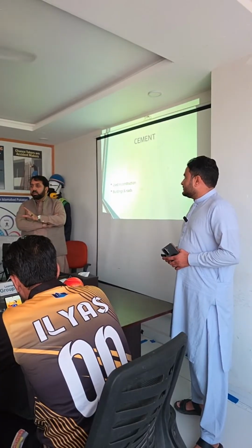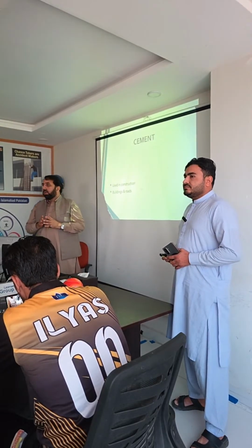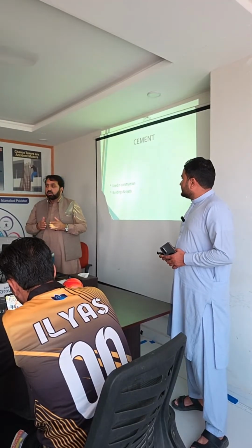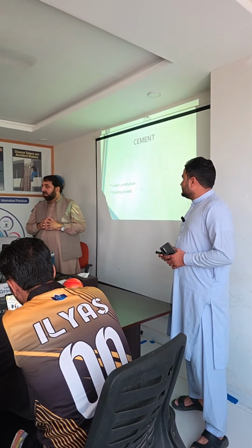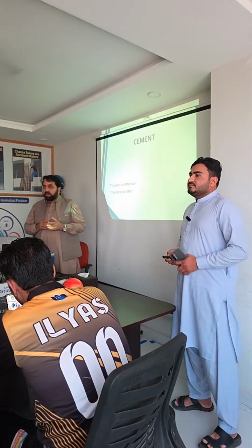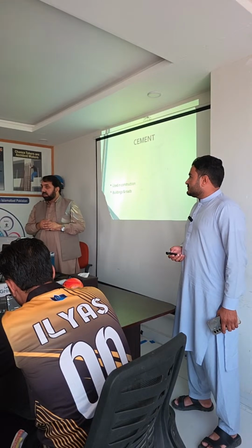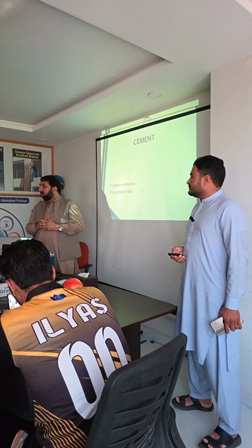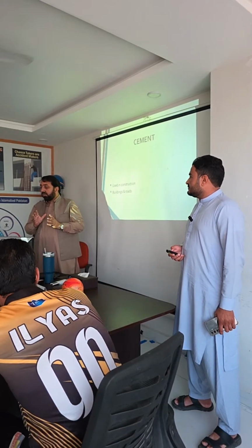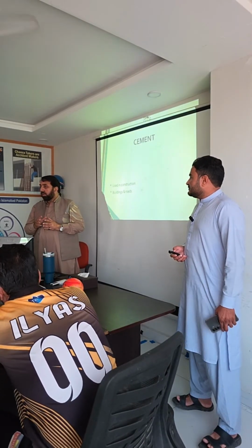Mostly carbon monoxide is produced whenever you are burning fuel. Due to combustion, when fuel is burning, it will produce mostly carbon monoxide. Like in our homes, we burn natural gas in our kitchens, in gas heaters, and nowadays the instant geyser in the washroom. These are all sources where carbon monoxide can be present due to the burning of fossil fuel. If it is in a high ppm, it can kill people in 3 seconds.